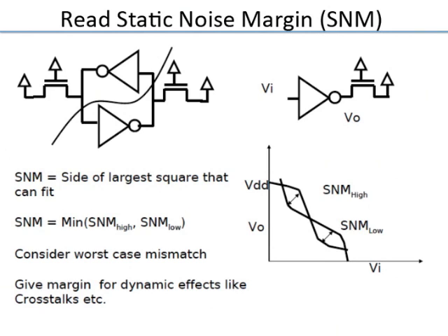And then for each run you get this DC transfer curve, you record the minimum eye opening. When you do it over thousands and thousands of runs, you have to do enough runs, then you get a distribution of the static noise margin. Then you have to say, okay, is that cell design good? You designed a cell with these sizes and for these voltages, but when you do this statistical Monte Carlo analysis, what you expect is a certain mean noise margin SNM and a certain sigma. So you have to make sure that you have enough. Typically, because you have millions of cells, you have to ensure plus minus maybe 5 sigma, right? The mean minus 5 sigma still is a positive number.